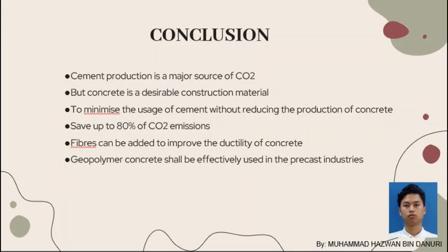The geopolymer binder is a low carbon dioxide cementitious material. It does not depend on the calcination of limestone that generates carbon dioxide. This technology can save up to 80% of carbon dioxide emission caused by the cement and aggregate industries. Due to the high early strength, geopolymer concrete shall be effectively used in the precast industries so that huge production is possible in short duration of time.